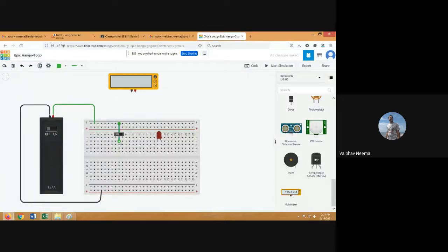Now the next, terminal number 2. If you select terminal number 2, whatever potential you apply onto it is common for terminal number 2. So suppose I select this third dot in terminal 2, then you connect that with this terminal, the anode of this LED.